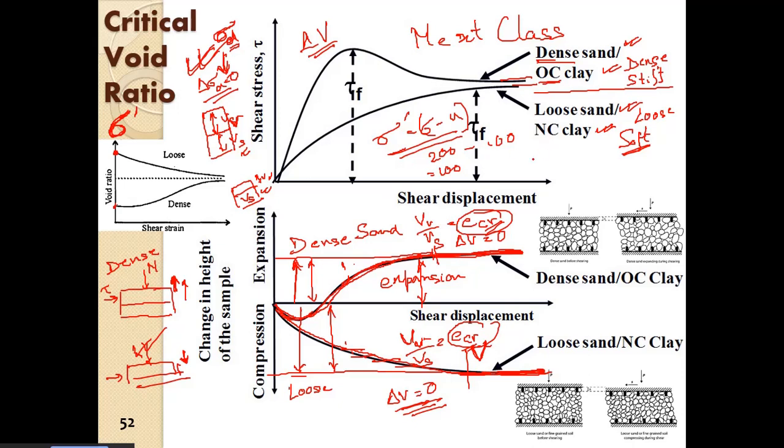If I take total stress 400 kPa and pore water pressure 300 kPa, we are at the same effective stress of 100 kPa. So for both of these conditions of total stress and pore water pressure, the soil has an effective confinement of 100 kPa. So these two soils will behave exactly the same way. So I am saying effective confinement.